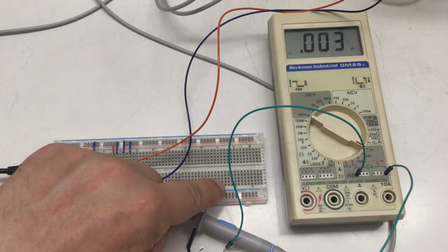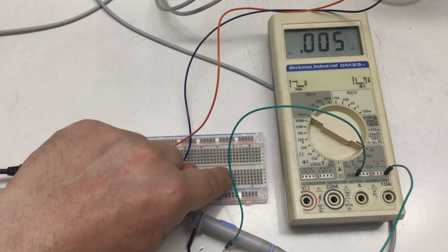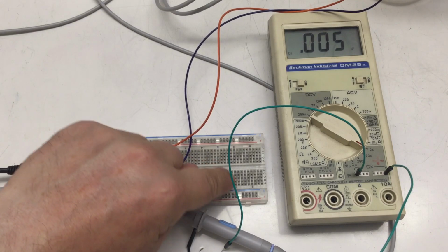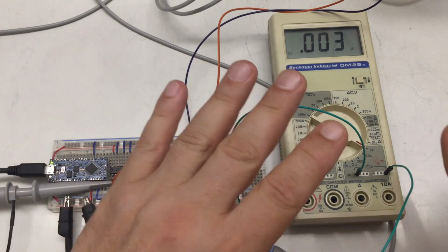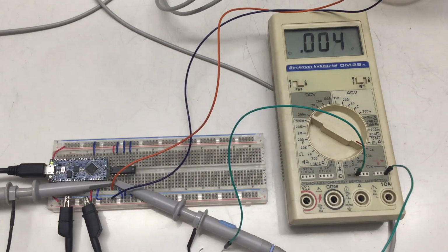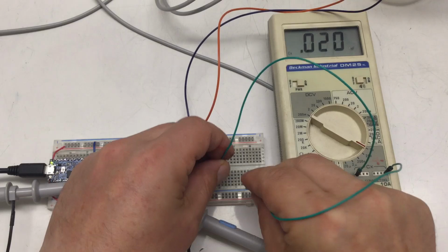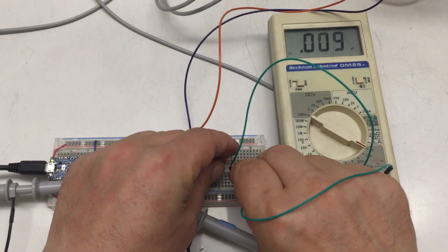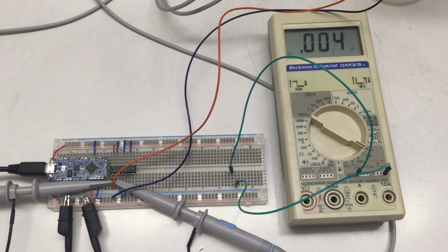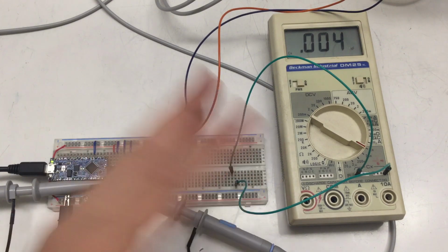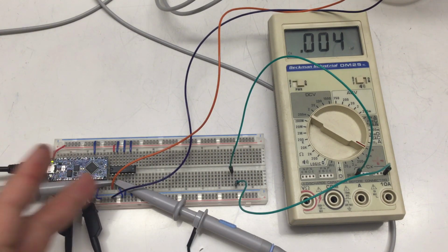However, if I try to measure the capacity between two adjacent rows of pins on my breadboard, measuring these small capacities is not simple, but we are now with leads at 3 picofarads, and I connect the leads somewhere at some adjacent rows, and we are at 4 picofarads. So there we have at least another picofarad of capacitance.